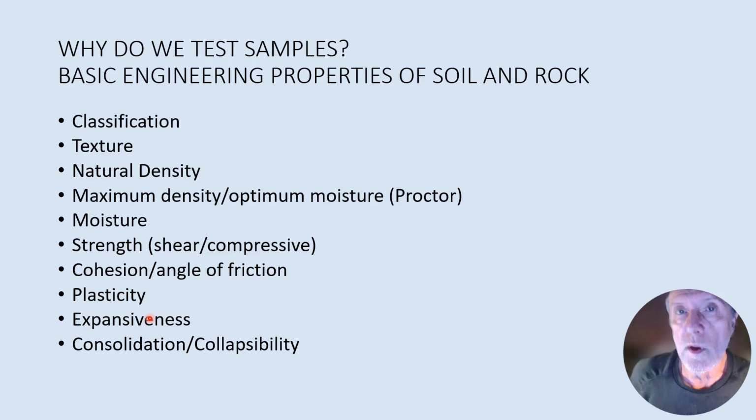Expansiveness, this can be critical in some soils and areas. There are certain clays where if you add water to these clays, the soil will actually swell or expand. So you want to determine that if that's going to be a factor during your construction. Consolidation, some soils actually compact or consolidate and lose volume under loads.